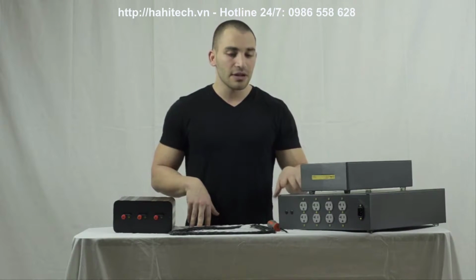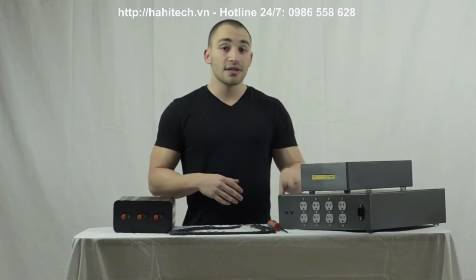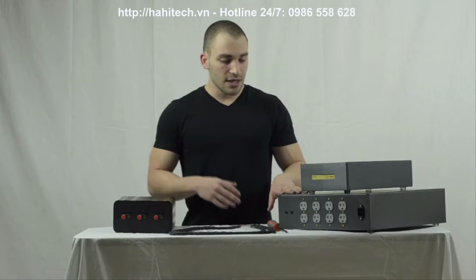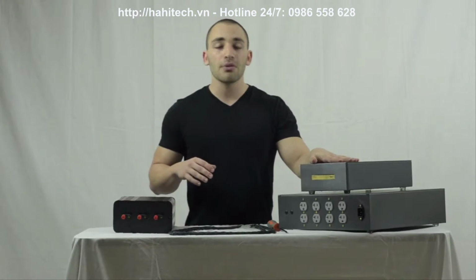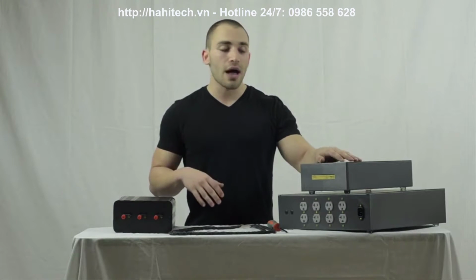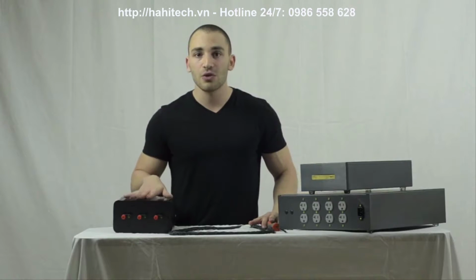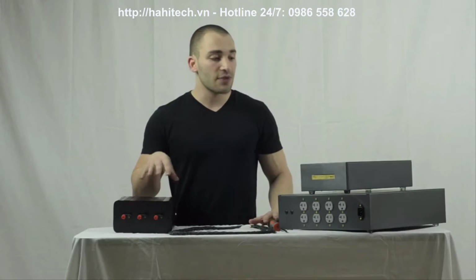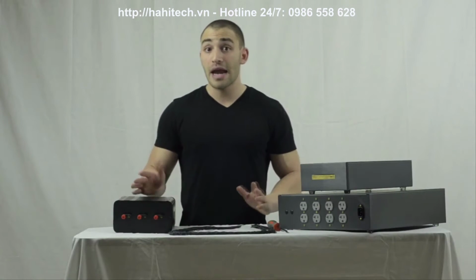So it has a fairly high impedance path to travel through and isn't as effective. So when you connect your device, whether it's a CD player or an amplifier or just a power supply, to the Colossus, you're actually creating a very low impedance path to ground for the shield, and that's very good for reducing noise quite dramatically.